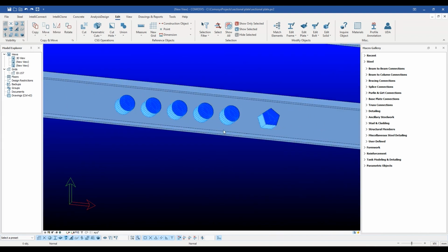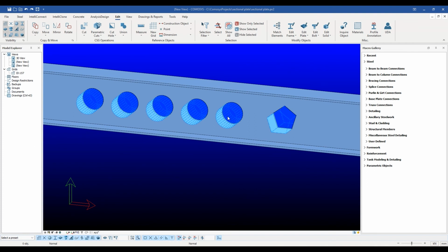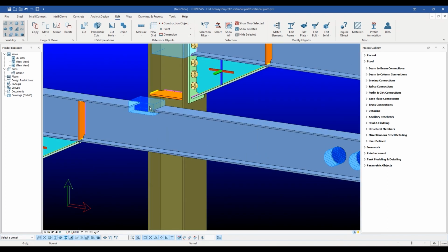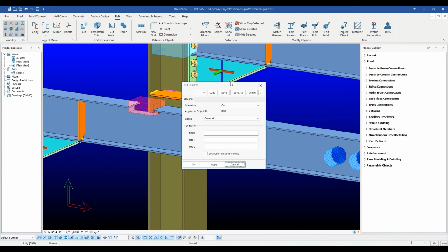Cuts are applied to the object in the order of creation. Deleting any will cause the whole object with all remaining cuts to be recalculated. Double-clicking on the cut object opens up its property window. In most cases, changing the properties of cuts is not needed, but there are a few properties of interest here.